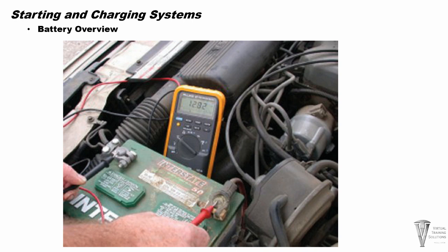A weak or under capacity battery also may overheat the alternator and starting systems. You cannot test an electrical system accurately with a weak or under capacity battery.